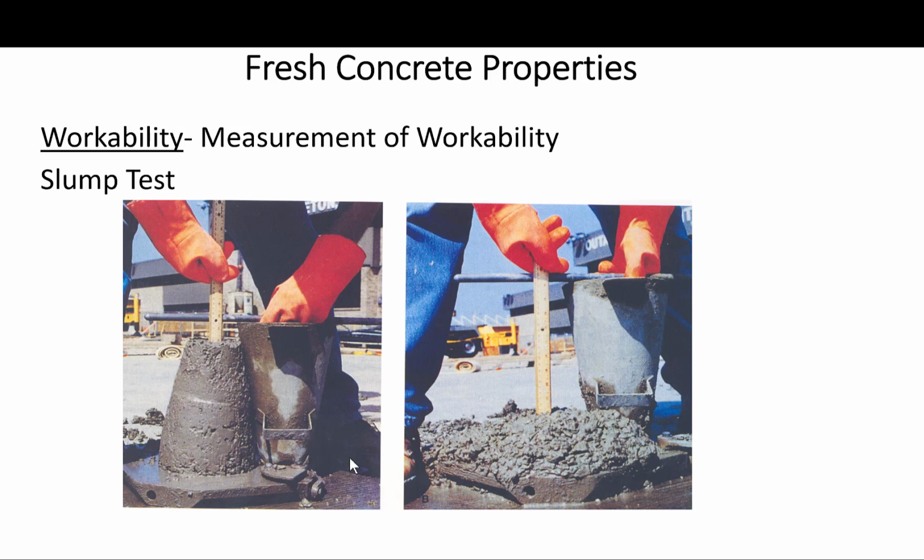So it has been suggested that workability should measure at least 3 separate concrete properties. 1, compactability, which is the ease with which concrete can be compacted and air voids removed. Mobility, which is the ease with which concrete can flow into forms, around steel and can be molded.